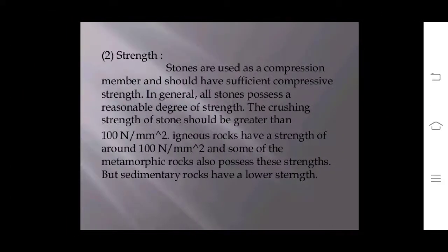The next property which is useful for construction stone is strength. Stones are used as compression members and should have sufficient compressive strength. In general, all stones possess a reasonable degree of strength. The crushing strength of stone should be greater than 100 Newton per mm square.